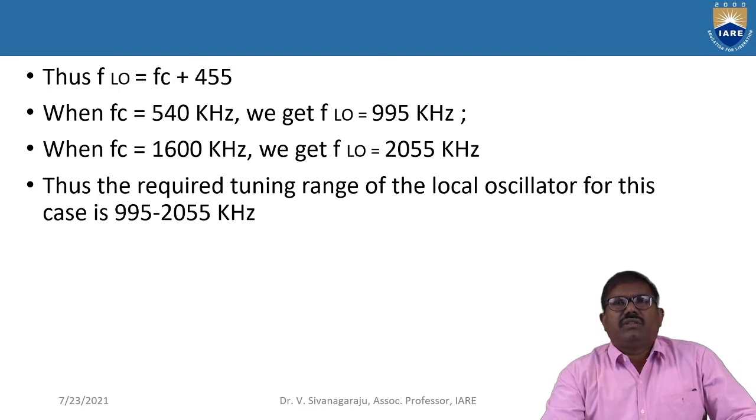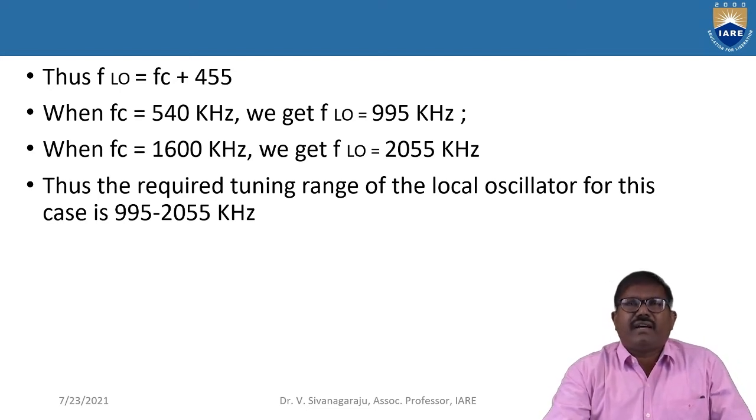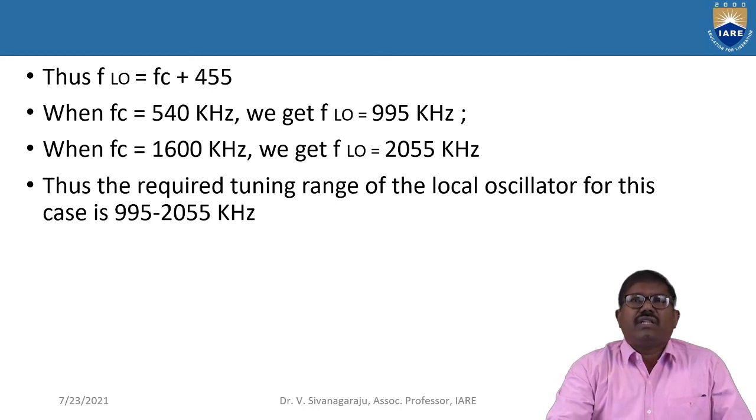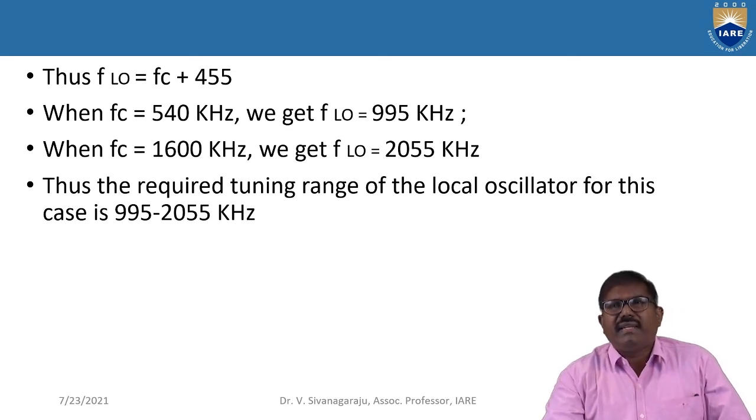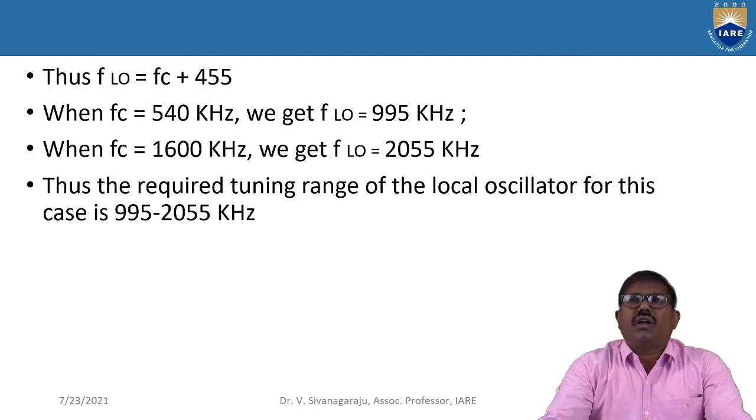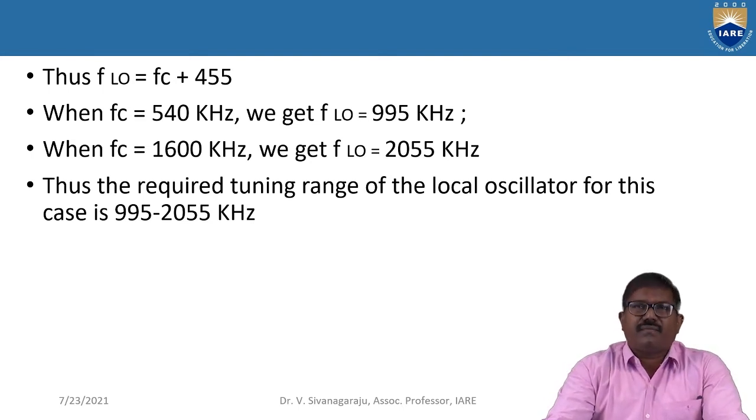So FLO, the local oscillator frequency, is equal to Fc plus 455. Here we are going to find the local oscillator tuning frequency range.